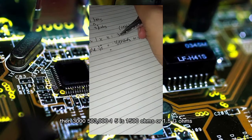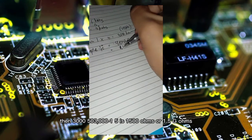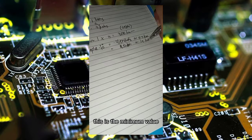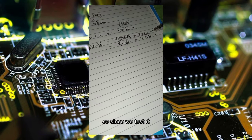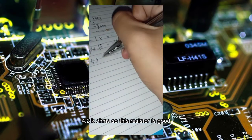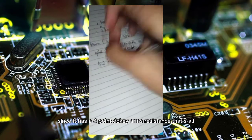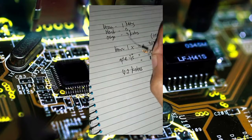Then 3,000 minus 1.5 is 1,500 ohms or 1.5 kilo ohms. This is the minimum value and this is the maximum value of this resistor. So since we tested 4.2 kilo ohms, this resistor is good since it has a 4.2 kilo ohms resistance. That's all.